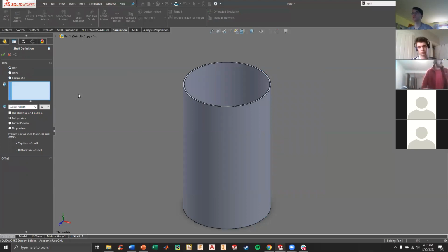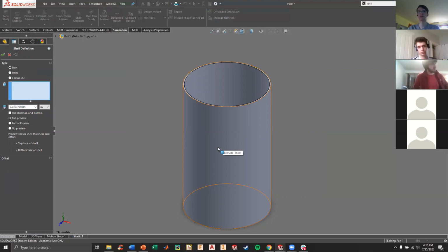Okay, so you can come in here, and like I said, we've been doing all of this as 3D solid models. So you get 3D meshes, tetrahedral prisms, I don't know what they are. And then all the forces are solved between those meshes. There are also 2 optimizations you can make. One is turning the mesh into essentially a surface, so it's just a 2D mesh. And the other is turning it into a 1D mesh, which is used for a beam.